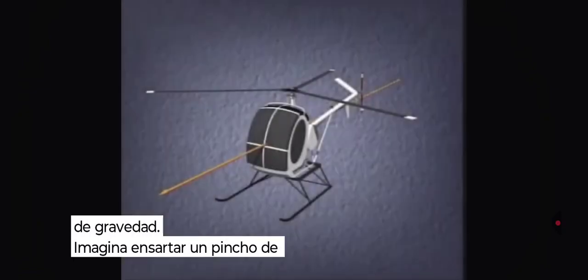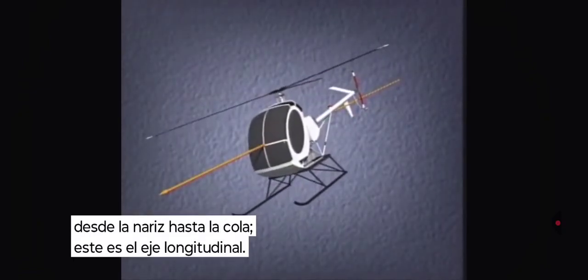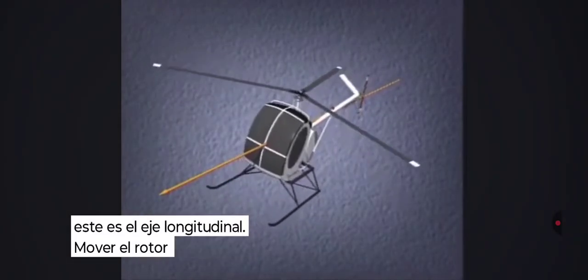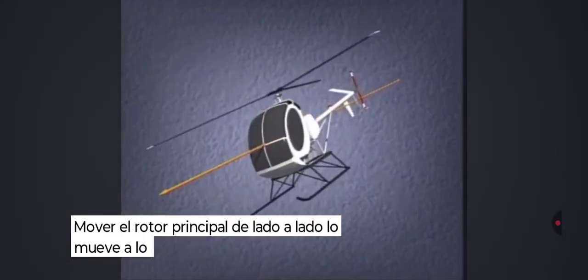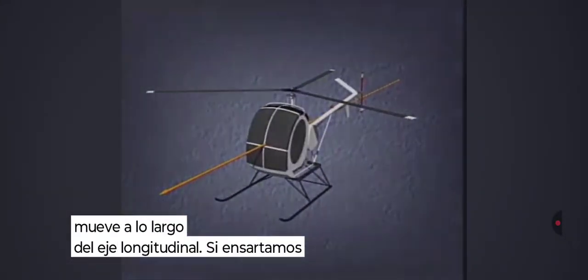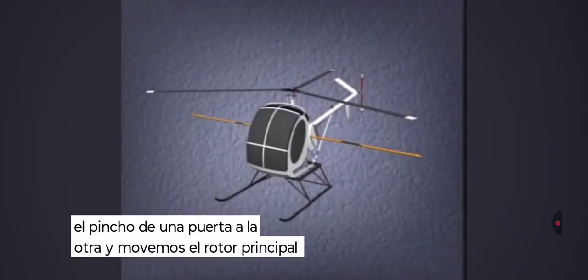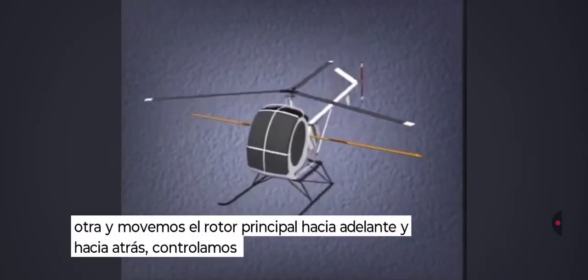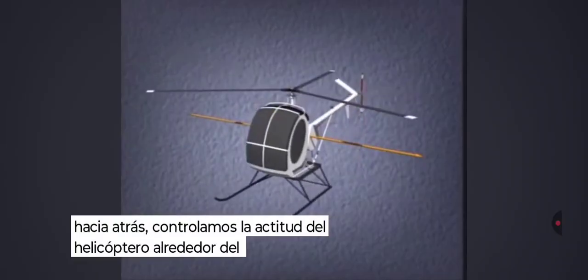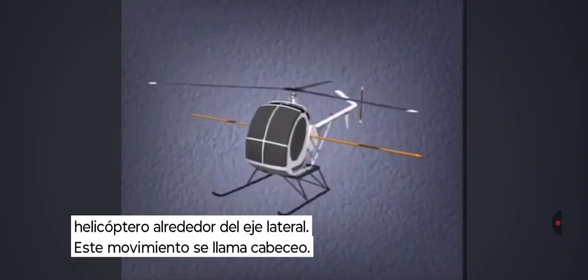Imagine running a shish kebab skewer from the nose to the tail. This is the longitudinal axis. Moving the main rotor side to side is moving it along the longitudinal axis. Put the skewer through from one door to the other and move the main rotor front and back, and you control the attitude of the helicopter about the lateral axis. This motion is called pitch.